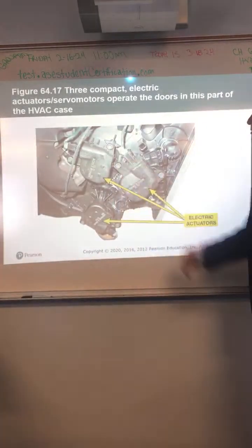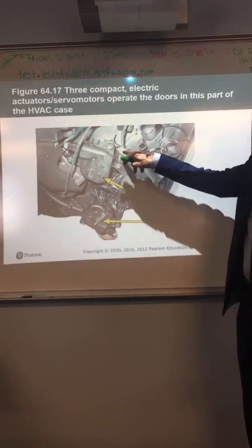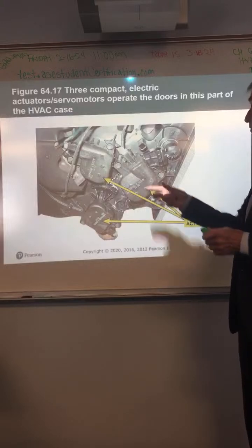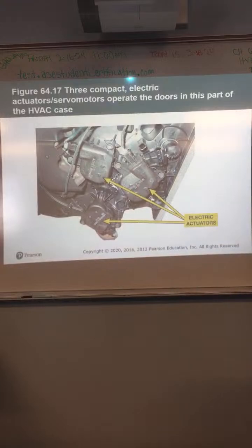I will tell you this, don't plug one of these in and try to see if it works without it being connected to the HVAC system there, because it will over center itself, go through far, and it'll mess up the actuator. So don't plug it in and just see if it works, okay, with it not installed.